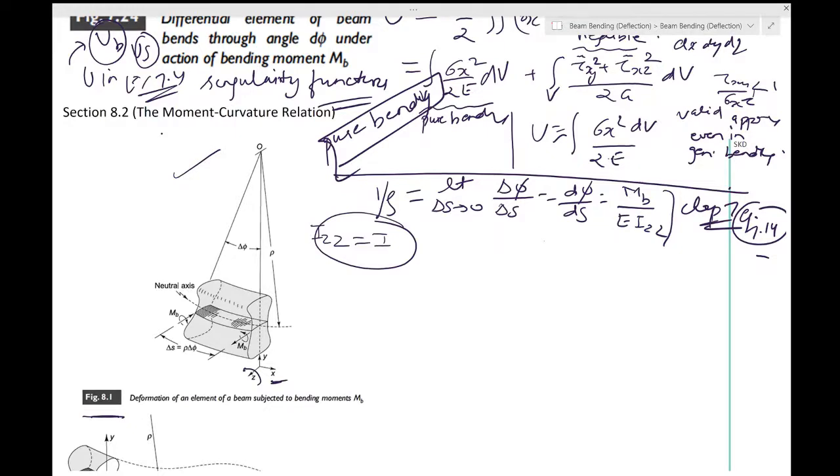We make a simplifying assumption. We assume that the shear forces which necessarily accompany a varying bending moment do not contribute significantly to the overall deformation. This is an assumption, and a new assumption. Please don't treat it like an assumption you have already seen or known before. It has never come before until now, and it's a very new assumption.